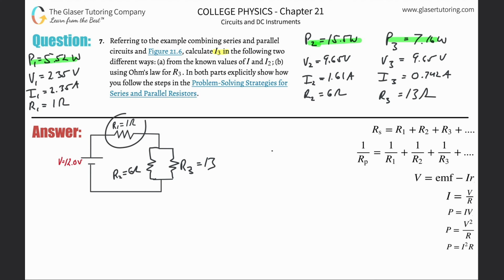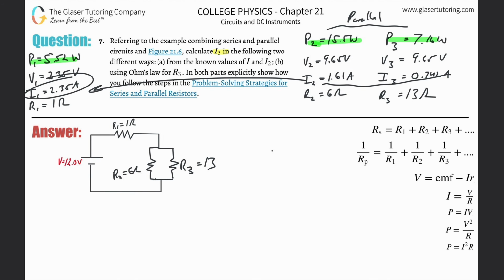Look, the voltage over number 1, plus, now don't look at these two separately, because the voltage over these two is constant, plus, let's say the voltage over 2, if you added those two together, guess what you're going to get? 12. Right? If you added then these two currents together in parallel, these are the two parallel arrangements, those two currents, you're going to equal then the current also flowing through the series element. All right? Hopefully this makes sense.